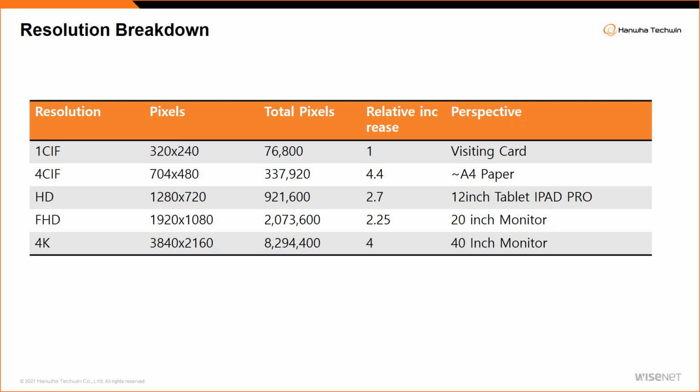More details also means more bandwidth, more data, right? So 4K is like 8 million pixels or 8 megapixel. You're using the 4K camera to cover the same training room or same entrance, but you get more detail because you are providing more pixels. So simply put, higher the resolution, higher the pixels, higher the bandwidth, higher the storage, higher the data. All right.